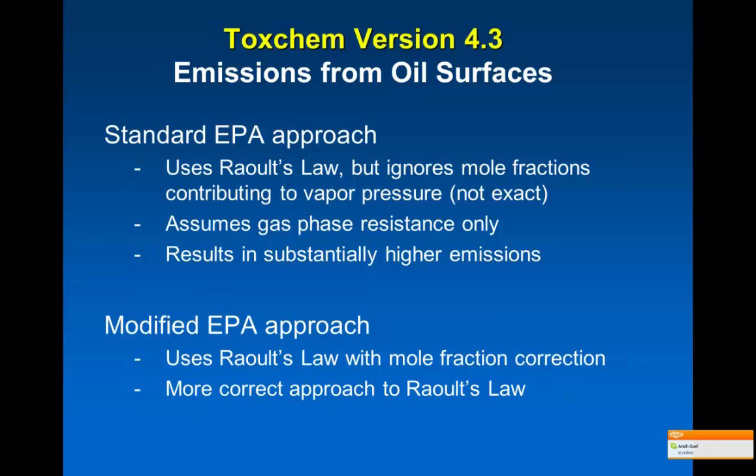So just to highlight some of the important points of these approaches, in the standard EPA approach, we are using the Raoult's law, but in this particular implementation, the mole fractions are actually ignored in estimating the vapor pressures of any given specific compound. Also, the gas phase resistance is assumed, and the water phase resistance is ignored in the mass transfer coefficient calculations.